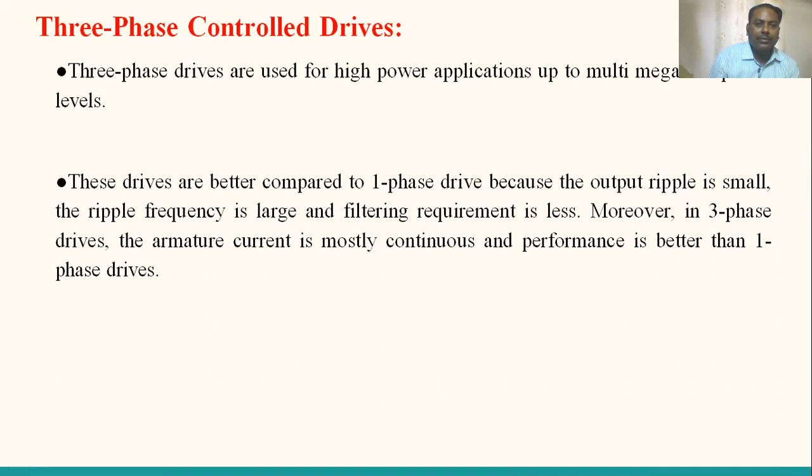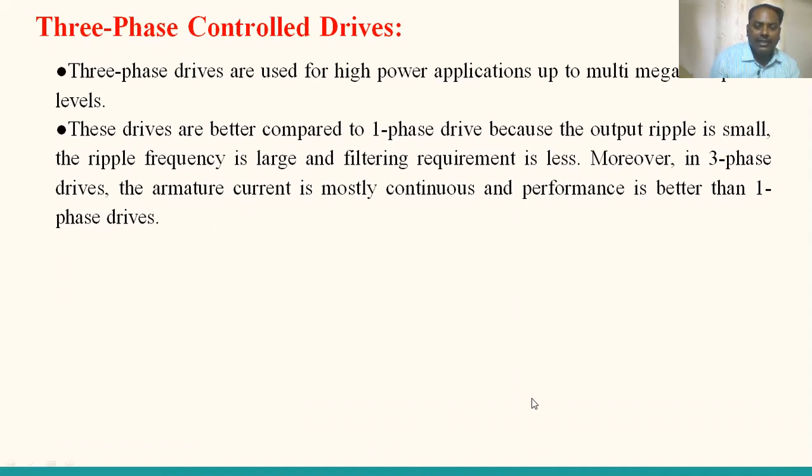Yes. So when compared with single phase drives, what are the benefits of three-phase drives? Let us have a discussion here. Generally, for single phase supply, every 180 degrees there is a pulse. With a sinusoidal single phase supply, every 180 degrees there will be a pulse change. But in the three-phase system, every 60 degrees there is a pulse. As per general awareness, as the pulse number increases, the ripple content and the harmonic content decrease.